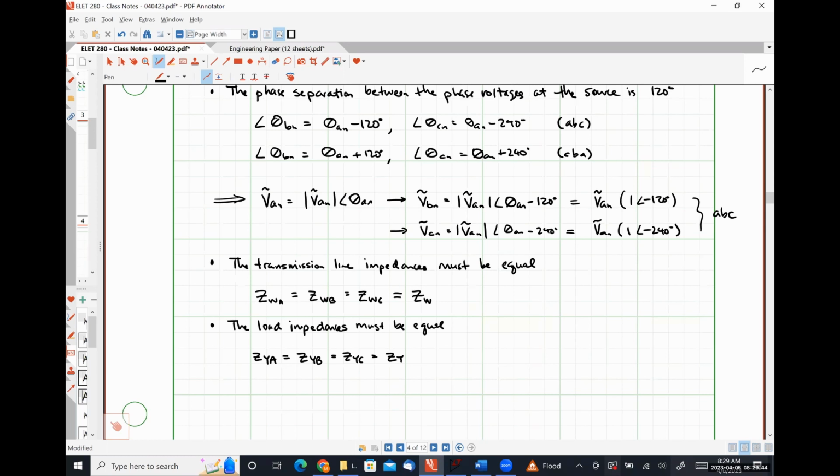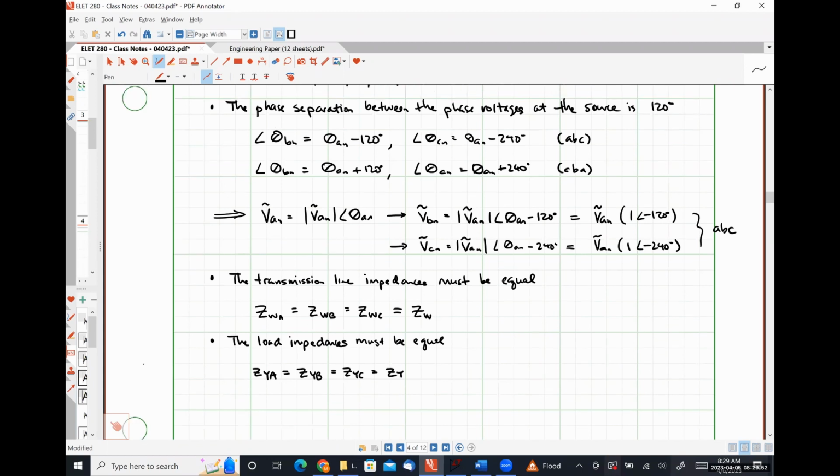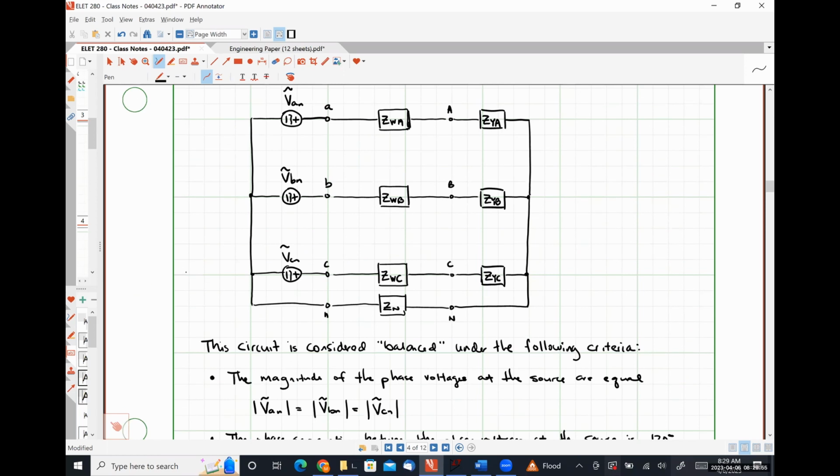All of those are effectively just small motors that are moving refrigerant from one point in a system to another point in the system and managing the pressure inside the system. Well, the compressor is typically a three-phase motor, but the blower fan is typically a single-phase motor, which means it's going to be connected across only one set of these phases, right? So that means that you're going to have an unbalanced system. So if you were building a system that had multiple HVAC units, you would want to connect one of the blower fans between the A and B phases, another one between the B and C, a third one between the C and A, so that overall things get as close to balance as possible.